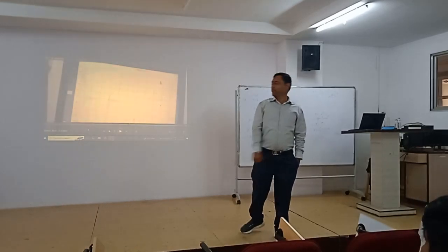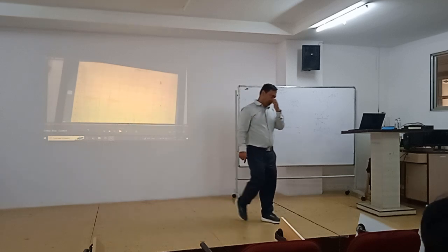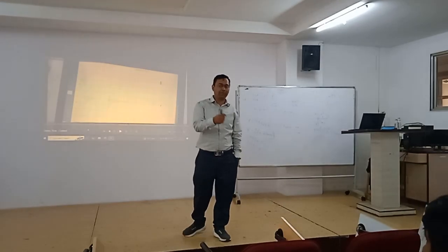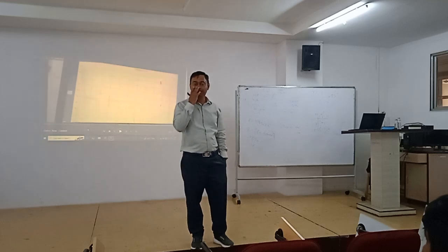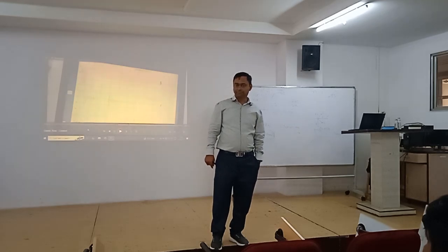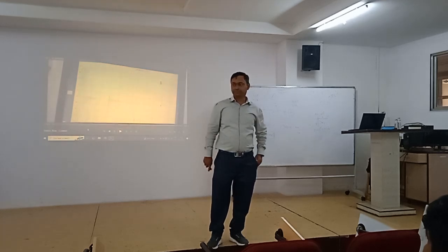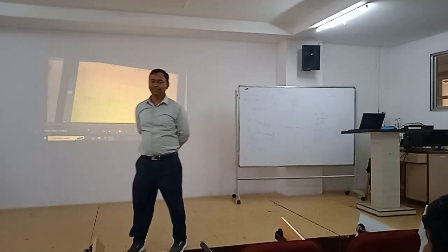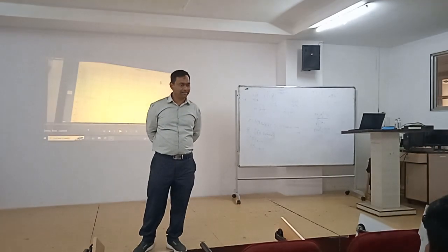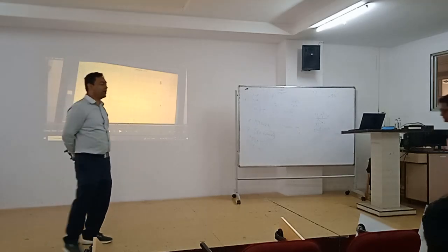Now suppose we reduce the disturbance, suppose we open the valve fully. Then what will happen to motor speed? Decrease. Motor speed will gradually decrease because it will reach the desired value. What will happen to the flow? Flow will increase. It will try to reach its set value. Directly? Gradually. To max.